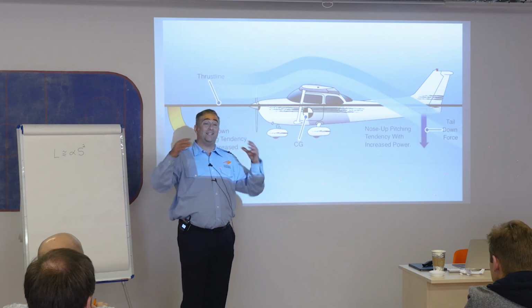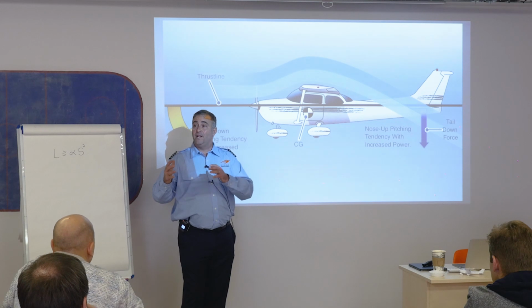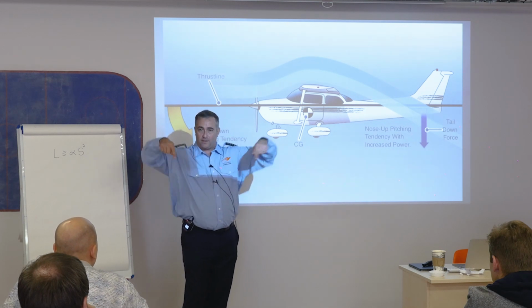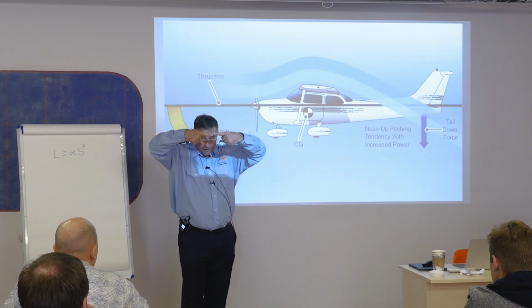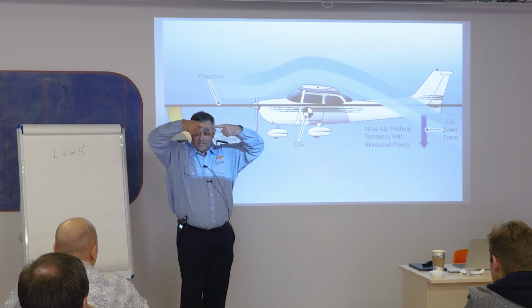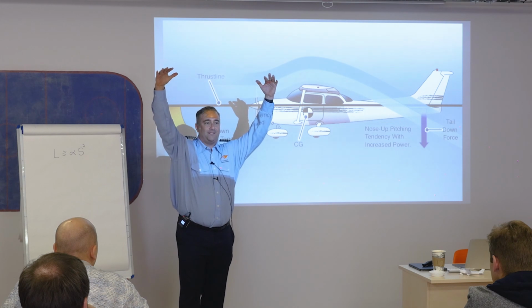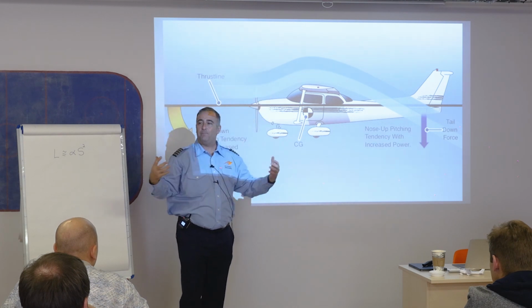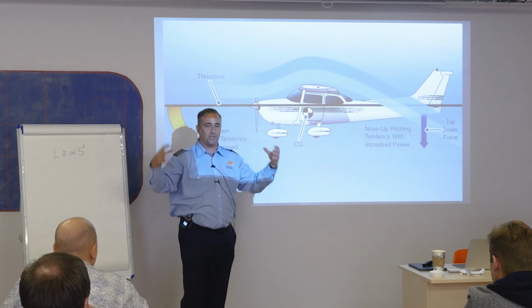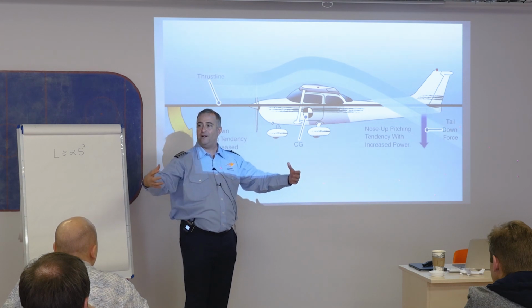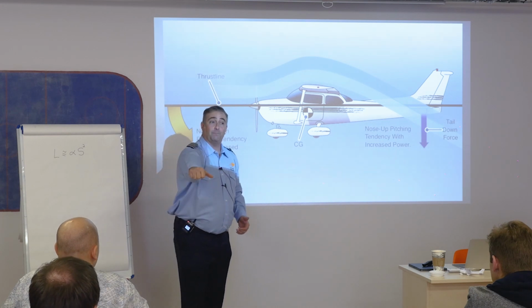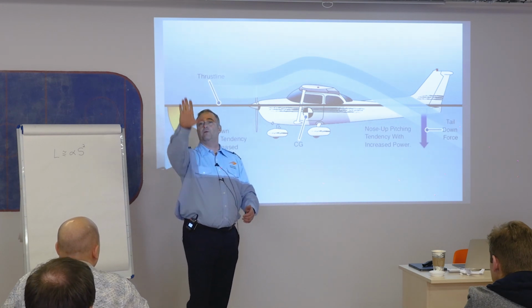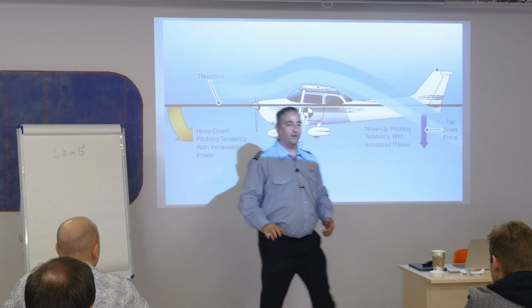And then the last engine that they put on this thing was so big, they couldn't fit it under, the landing gear folds up on a 737 like this. So the landing gear touches in the middle. They couldn't put bigger landing gear on it and make it stand up taller. They had to put bigger engines on it, more efficient. So the engines they put on it, they made the engine go more forward. And then when pilots applied power with this thing, it created a tremendous amount of pitching up moment, right?